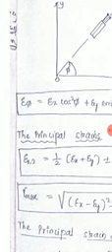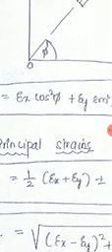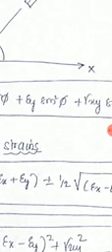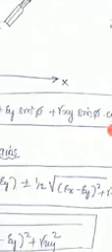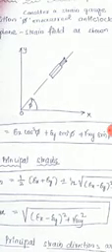If you know that, now we can calculate the strain at a particular direction and the stress at a particular direction, by using this available equation. Epsilon phi is equal to epsilon x cos square phi plus epsilon y sin square phi plus gamma xy sin phi cos phi. This equation is given in mechanics of materials. Already you know that. Next, if you know the angle, we can use this equation to calculate epsilon x and epsilon y.